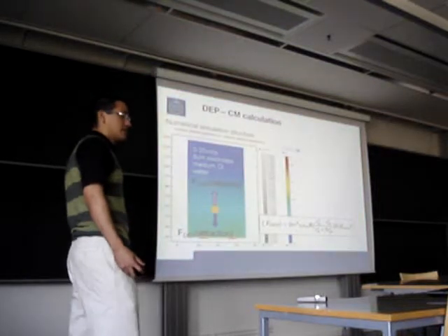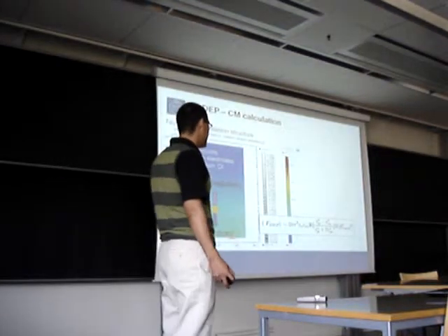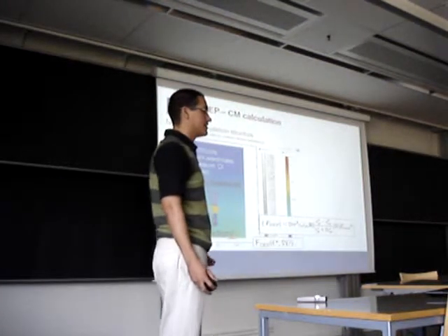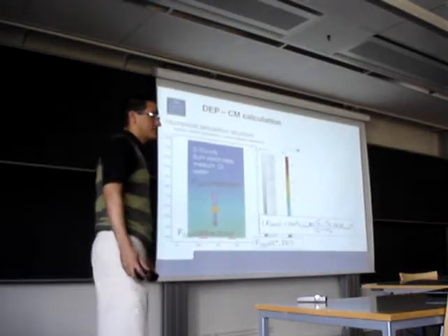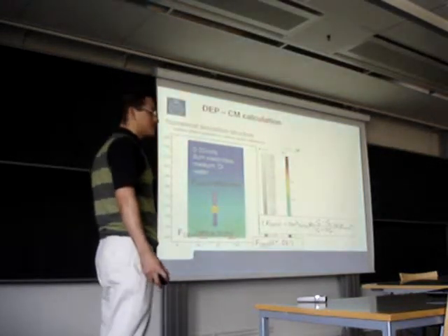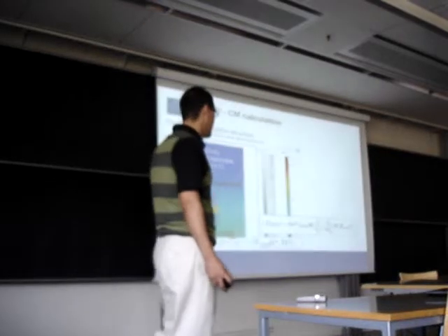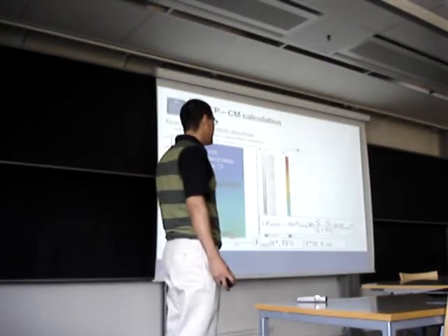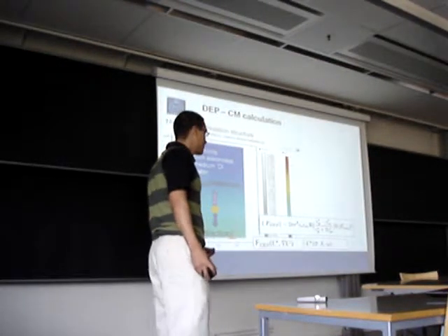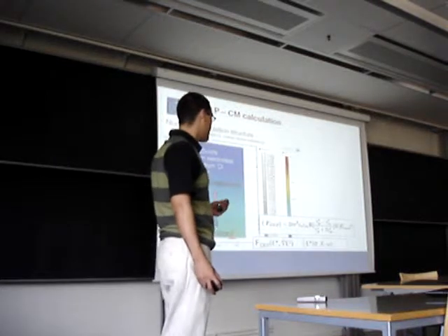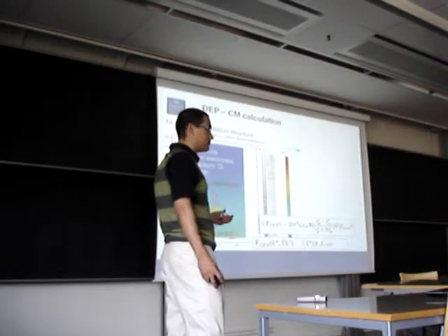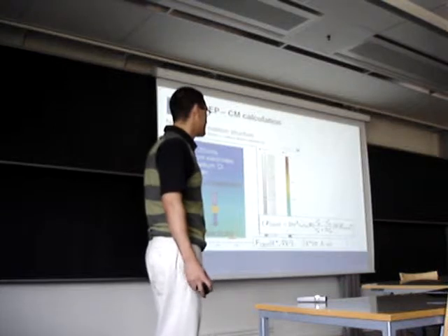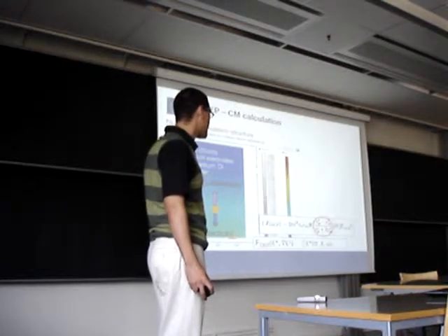The formula for dielectrophoresis is that one. We can see that it depends on the complex electric properties and the gradient of the square of the electric field. This complex permittivity is based on the conductivity of the medium, the permittivity, and the frequency that is applied.